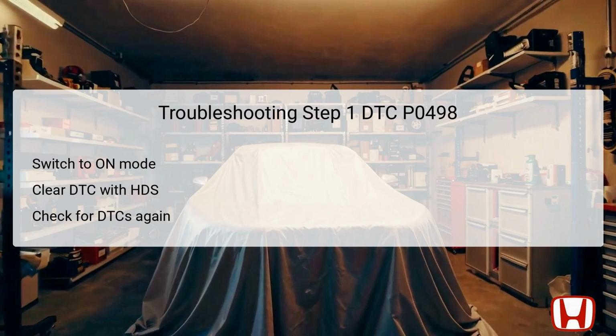Subsequently, you should check for any pending or confirmed DTCs using the HDS again. If DTC P0498 is indicated, it confirms the presence of an issue that needs addressing. If not, a further evaluation of the system may be necessary. This initial step lays the groundwork for an effective diagnostic process, helping to narrow down the focus of troubleshooting efforts.